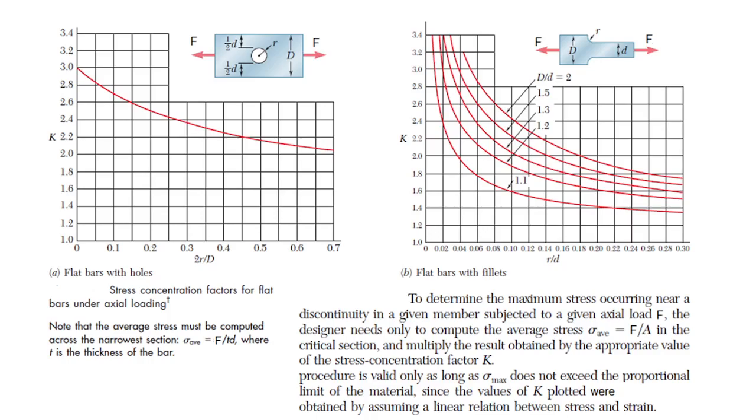In other words, use a finer mesh, a smaller size mesh. In the other parts where the geometry is monotonously the same in shape and size, use greater size elements. If we use this technique, we can continue to use an ordinary computer.